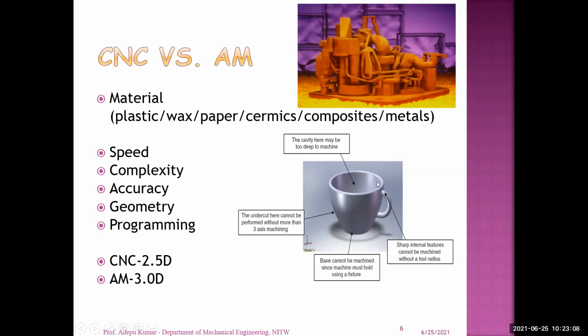If you are keeping the hot fluid in copper or aluminum, which have very good conductivity, the heat is transferred to the person who is holding the cup in his hand. So it is not advisable. The criterion for a material in hot condition is that it should have low thermal conductivity. Then you can select a material from the low thermal conductivity materials. In that case, ceramic is the best material to choose for holding a hot fluid in a cup.